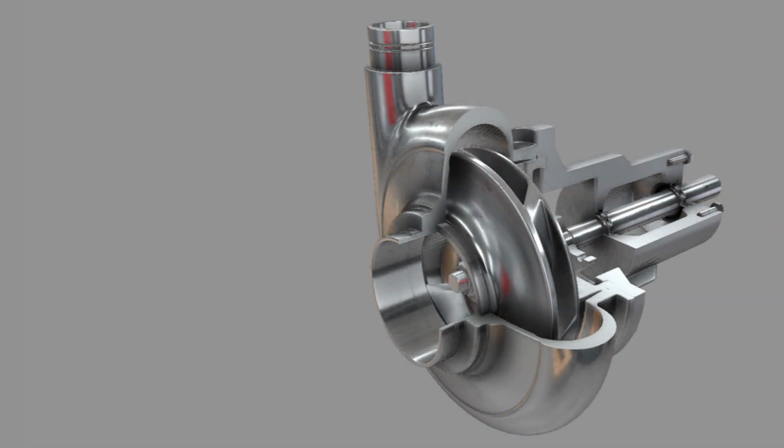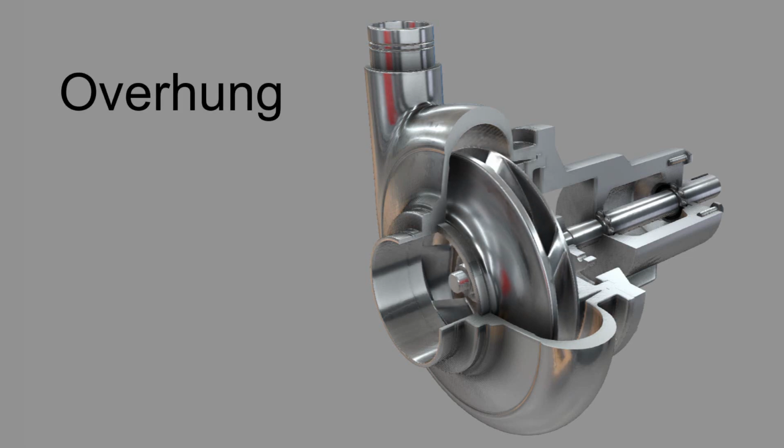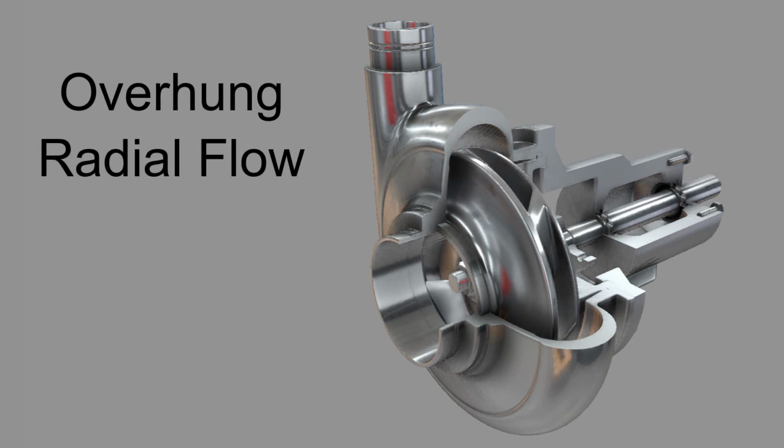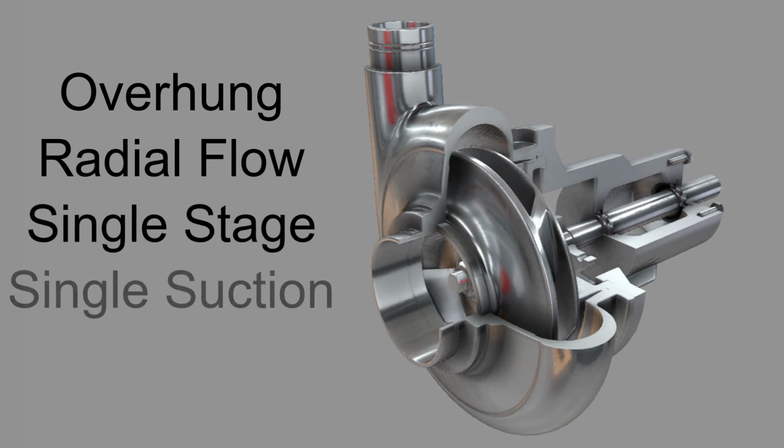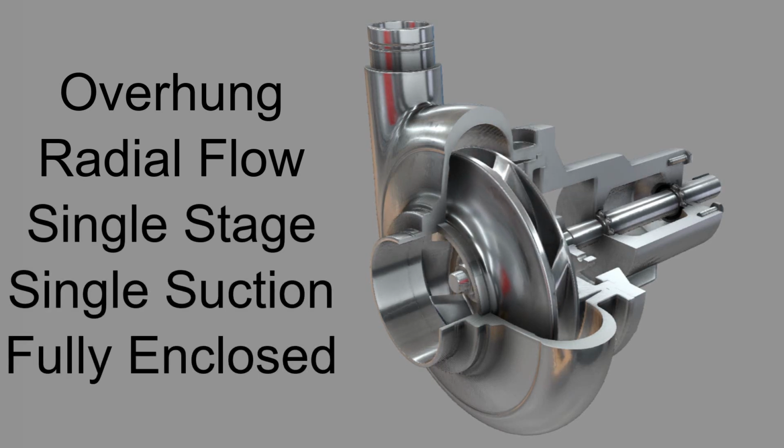So if we put together all that we've learnt from this lesson, we can see that the pump that we're looking at now is an overhung, radial flow, single stage, single suction, fully enclosed centrifugal pump.